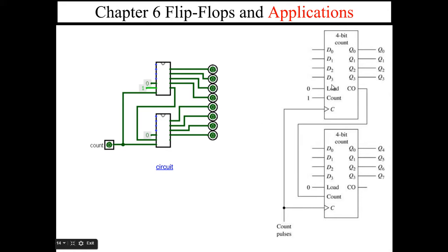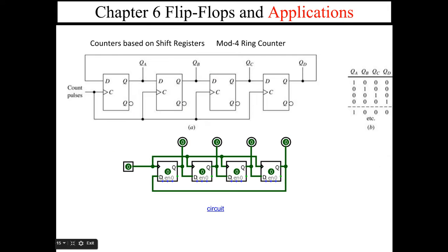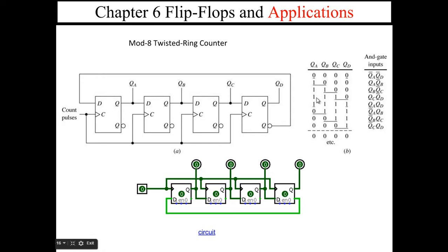And here we're using a carry mechanism to change this from a counter that counts up to 16 to a counter that counts up to 256. And here we've got a pattern going. We're not really counting. So it's just scrolling these ones across one at a time. And here we've got a 1, and then it fills up with 1s, and then the zeros start coming back, and that's done by feeding the negative output of this last flip-flop back to our input.